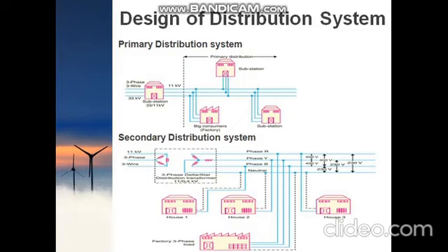you are going to convert your 3-wire system into a 4-wire system, and also you are stepping down the voltage from 11 kV to 400 volt, or 450 volt, 440 volt you can say. This is practically done to achieve one extra neutral wire for single phase consumers like small houses whose actual power demand will be less than 5 kilowatt. And obviously factory consumers also require a neutral wire for their internal connection.